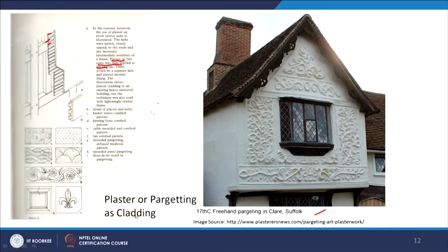So basically what you see is these plasters, and here again this whole set is a kind of decorative element, also referred to as freehand pargetting. Here you need to have a picture of what kind of imagination you are going to create on the facade, and at the same time it should not create very high bumps or lows. It has to be done a little carefully, especially the details, which is the edges, how they plaster it.